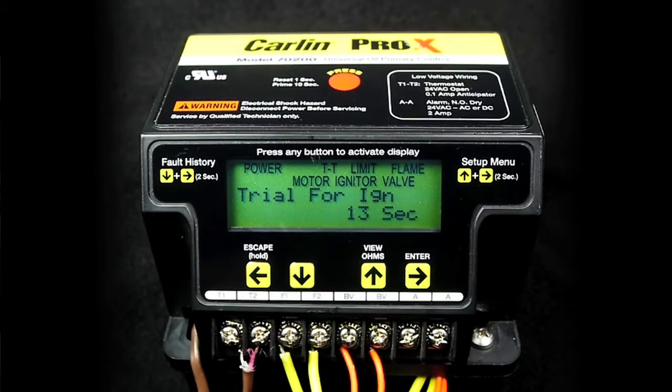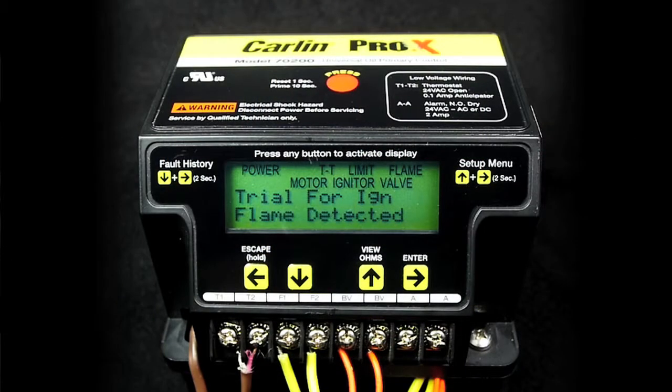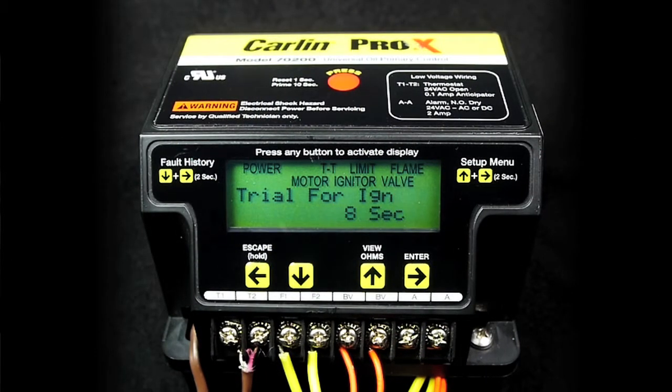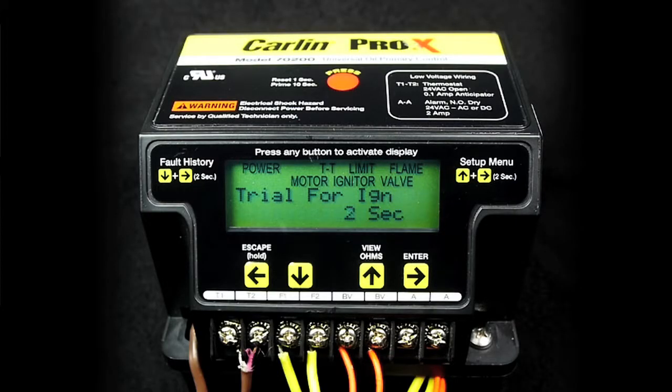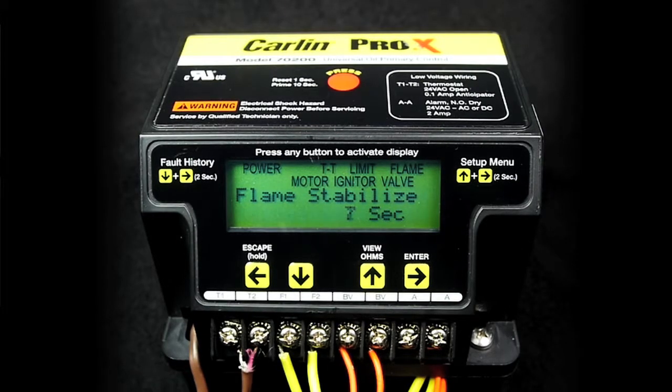Once again, the counter will count down the TFI sequence, and depending on the setup, this will be 15, 30, or 45 seconds. During trial for ignition, when the burner ignites, a brief message on the screen announces flame detected. Within 3 seconds, the message will return to counting down the trial for ignition. If no flame is detected, a fault message will appear. More on that later.